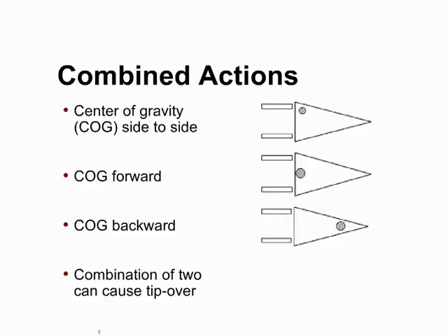For example, a forklift that turns a corner while driving up a ramp could shift the center of gravity too far backward and to the side, causing a tip over. A forklift moving forward with a capacity load could tip forward if forced to stop abruptly. Or, a forklift turning a corner with an unbalanced load could tip over if it drove into a pothole.